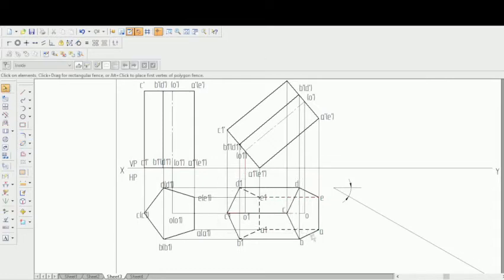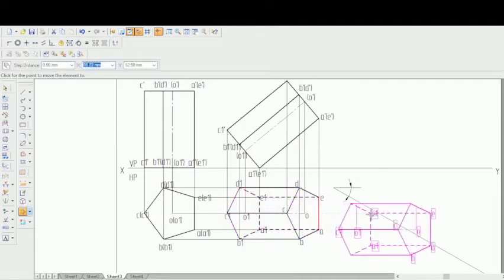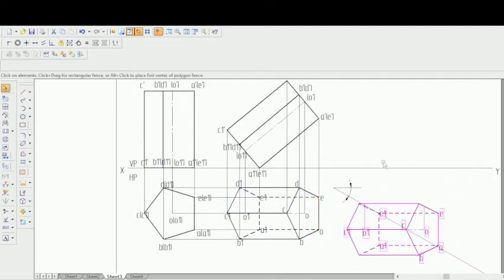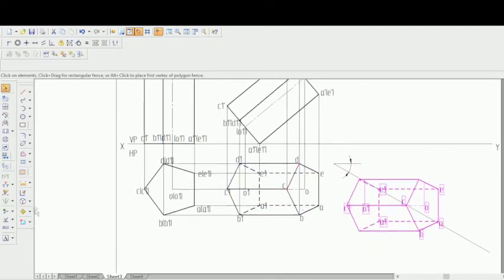Now let's select that completely, or you can even select it using the control key. Now let's move it. See that it's moved, and see that copy is switched on. Let me move from this point E1, and place it exactly on this line. Now I've just placed it. Still it is selected. Go to the rotate option, and see that the copy is switched off.